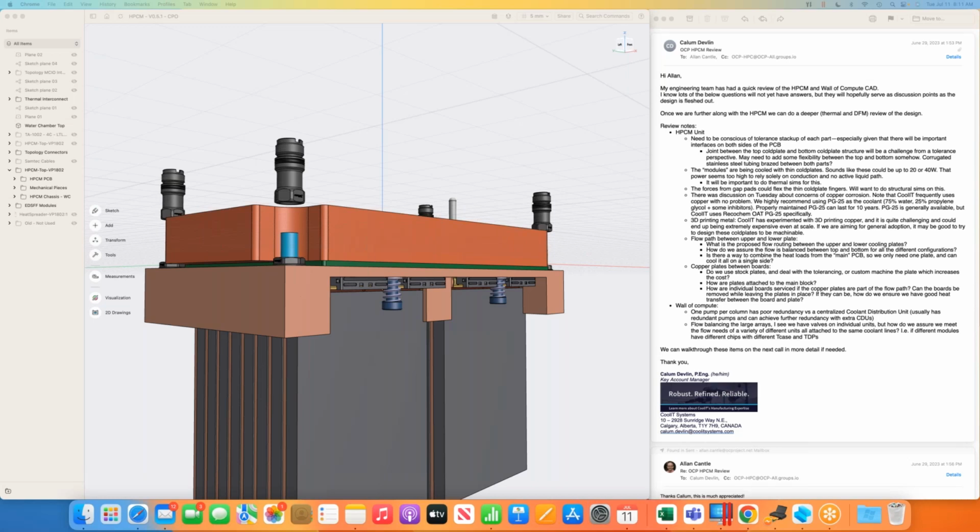On the stackup side of things, I can see a couple of areas. You particularly highlighted this top cooling chamber, and we've not actually shown the interface here. There will be a little water connection between this bottom plate and the top, but I was assuming it would be just a rubber sealed water joint. Is that not viable? You mentioned braze, are you thinking the two would actually be brazed together?